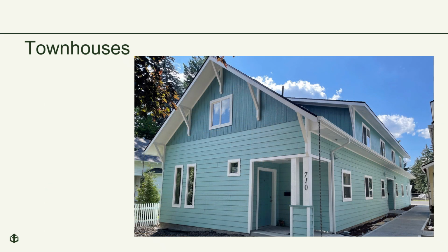Here's another townhouse building where the townhouse units are oriented in a row, but you'll note that each unit is not fronting the property. This 4-unit townhouse building also meets the IRC as it is 3 stories or less above grade plane, and each townhouse unit is open to a yard on 2 sides. But from an appearance standpoint, it may not look like what you would expect.